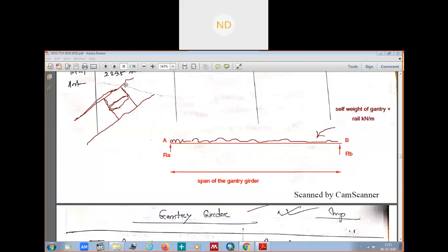We had got in the approach, minimum approach here, it was the minimum approach from here to here, and we got the maximum load, right? Okay, now these two legs of the crane girder are moving here on the gantry girder, and so the gantry girder will have the maximum shear here at the end, on the edge. We consider it to be here. Suppose this is your RC wheel of this crane girder which is moving on the rail section. So we can say this to be RC by 2, and this also RC by 2.